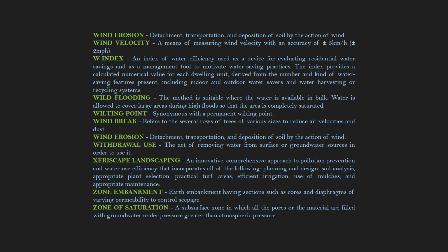Zone embankment: earth embankment having sections such as cores and diaphragms of varying permeability to control seepage. Zone of saturation: a subsurface zone in which all the pores of the material are filled with groundwater under pressure greater than atmospheric pressure.